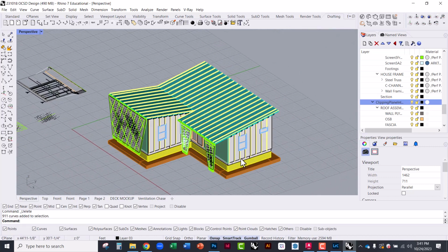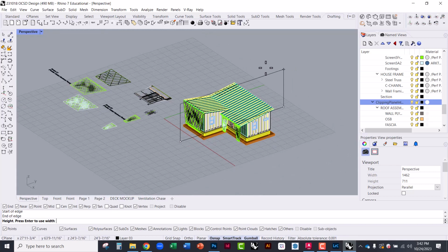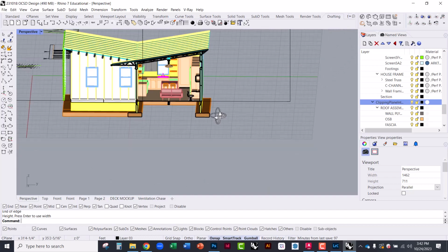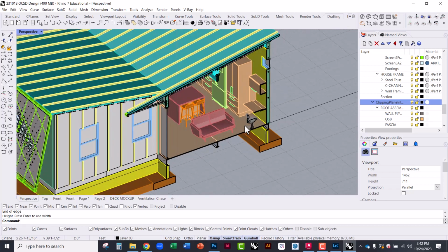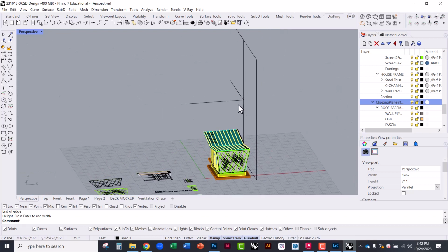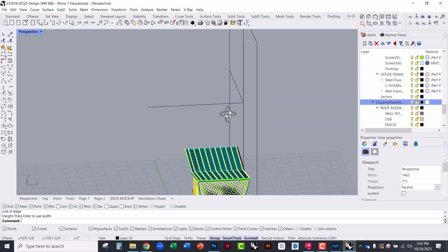So the way we do that is the clipping plane tool. If you type clipping plane, enter, and before you select anywhere, if you click vertical, you can have this be a vertical clipping plane. And we want this to be orthogonal to the plan itself. So I'm going to hold shift down before I click a second time and then zoom out, click a third time. And so you'll see that what's happening is this model is being sliced. And so this plane represents the clipping plane itself. This line represents the direction that we're looking.